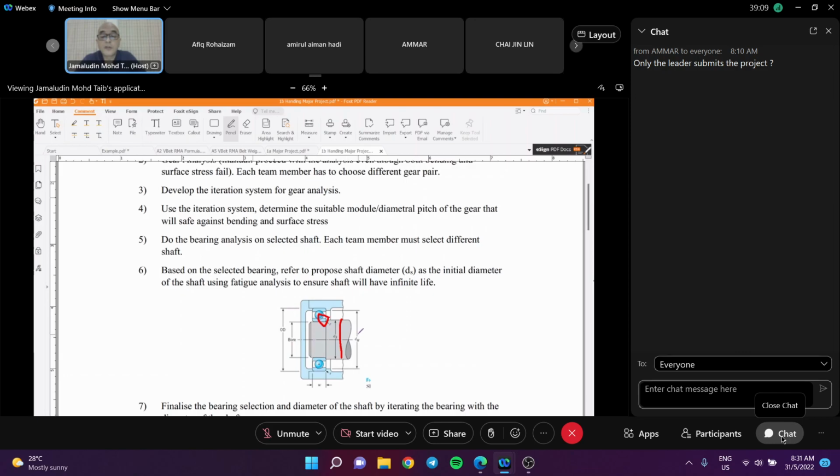This is going to be your first shaft, because if you run the diameter, it's going to be an iteration process as well. Remember, in the iteration process, shaft is d cubed, right? Because M over d cubed. I think with the new calculator, you can iterate very fast. That's fine. Remember, let's say bending is going to be 32 M divided by d cubed. It's going to be an iteration process, because imagine the Kf is going to rely on diameter and so on. So the iteration process goes on.